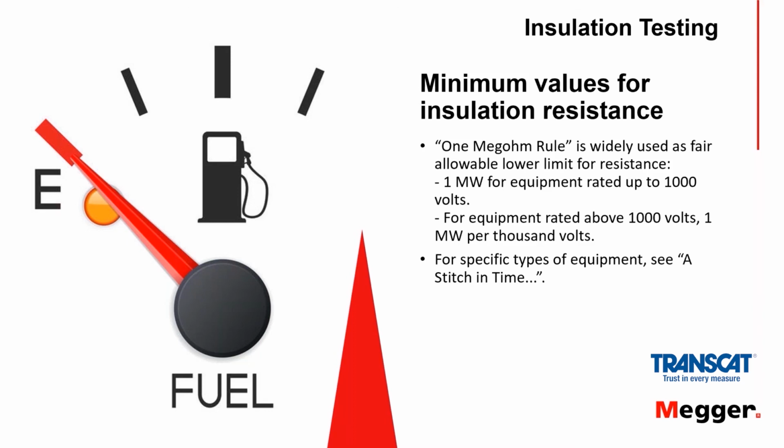It's where you have concentrated leakage, where there's a bad spot somewhere, that's going to break through to ground eventually. So that's what you have to worry about more so. And so if you're holding your insulation resistance value, even though it's not terribly high, maybe it's 100 megohms or something like that, but you're holding it, don't worry too much. But if it's dropping relatively precipitately, that's where it's going to break down and short out to ground. And so that's a bigger concern.